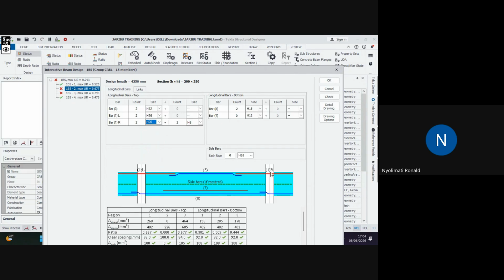But if you go to the field, most people, if you have designed this with 16, will also consider this joint to be 16. I don't know. But remember, there's maximum at supports. You understand? So if they say we need to use 20 here, it has to be 20. Like I check here, 20. Okay? So here is 20 at this support, here is 20 at this support. But in the middle, I can use 2T16. You understand? Then this one is resolved.